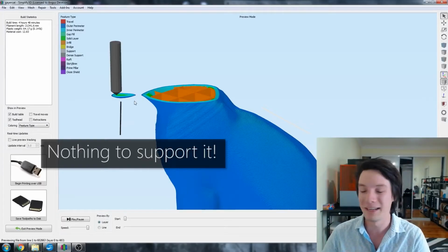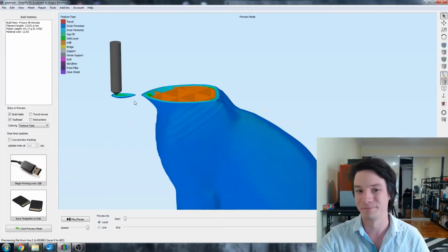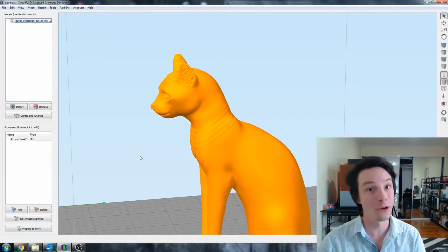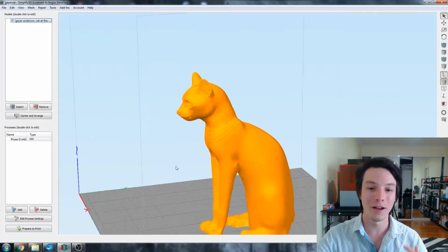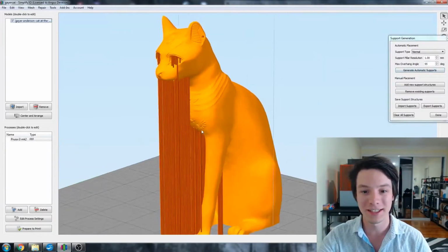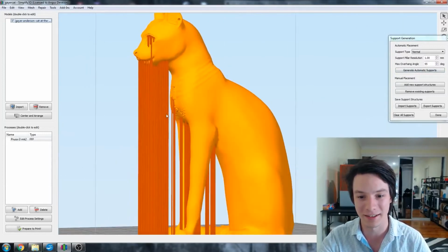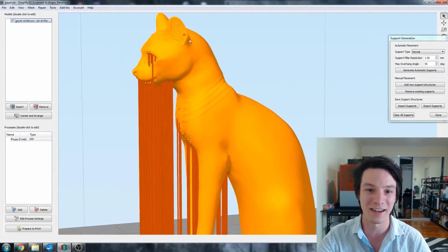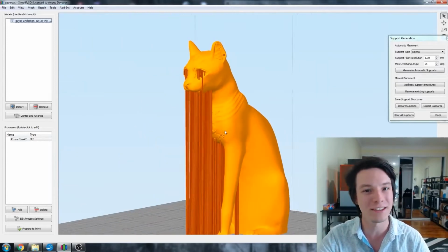So the reason this is important to understand now is because when we get into the next phase of actually putting our Rhino model into the software that the 3D printer uses, that software is going to add supports wherever it is needed. Now, typically the supports are easy to cut away with a scalpel or with a set of pliers after the model is finished, and so that's fine.